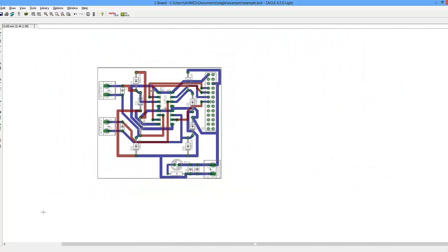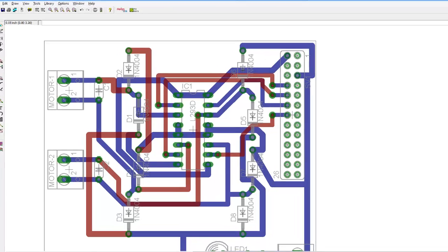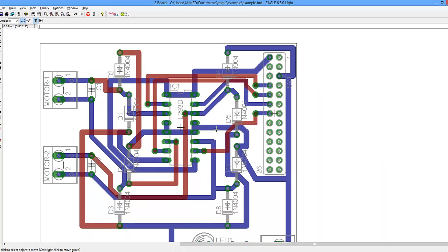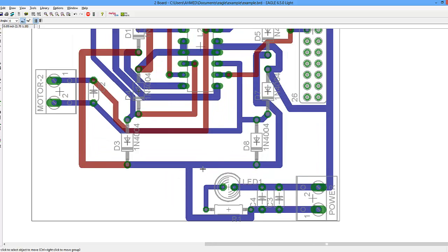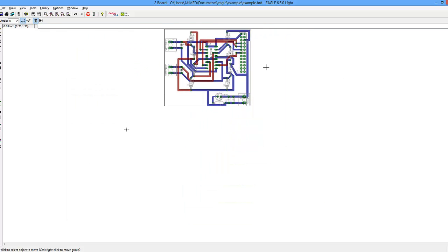Look, these dimensions were made for a board house or a PCB manufacturing factory. You are students or school kids or hobbyists who don't know better, so this is better for you. So the bigger the pad size, the easier for you to solder. The smaller it is, the harder for you to solder, and you will probably ruin the pad in the process. Okay, so the bigger, the easier for you to apply solder on. So with this done, that's the end of the tutorial.